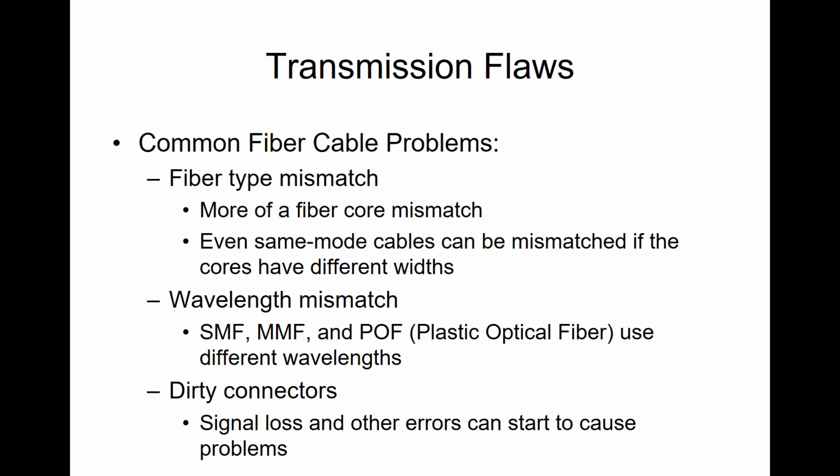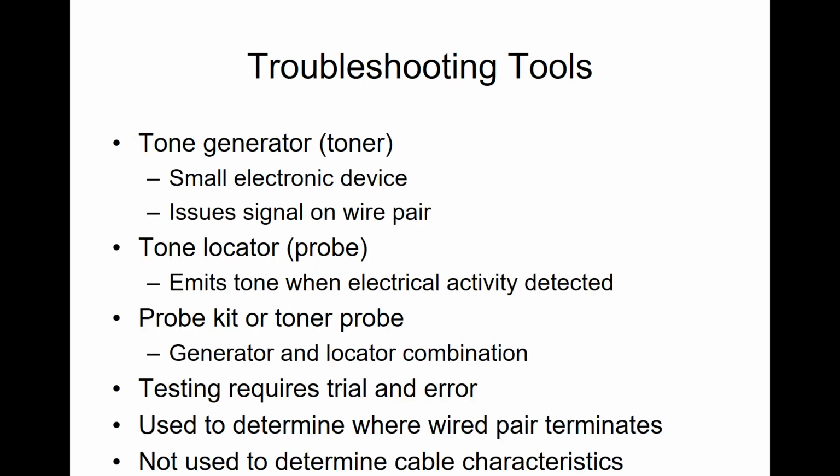We didn't take into account that we were in such a hurry to get it open, that we built this hospital, hooked it in, and it sort of worked, but we had some odd data connection issues, and we blamed all kinds of other things, because quite frankly, we went live about the time the hospital did. There was not a lot of time for prep, and what it turns out was we had a mismatch between the wave size and the fiber size, and so we had to end up replacing a whole bunch of transceivers to get them to work correctly.